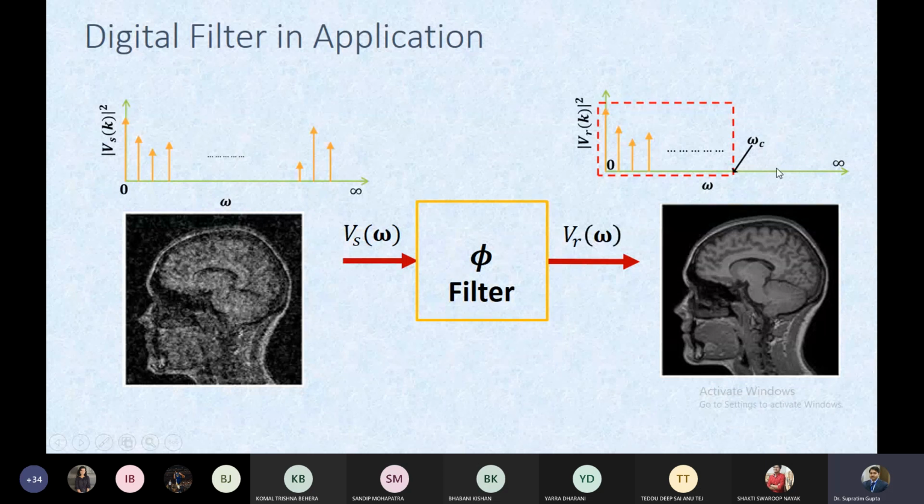But if omega c is, say, 300 hertz, and we are injecting a signal of, say, 600 hertz, that signal should be attenuated drastically, and the amplitude can be closer to zero. Okay, so the basic working approach for testing the filter is to apply a single tone frequency and then see the response, whether the amplitude remains as it is or gets attenuated. Okay,